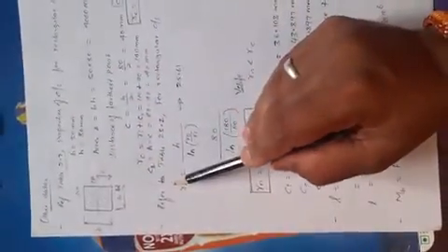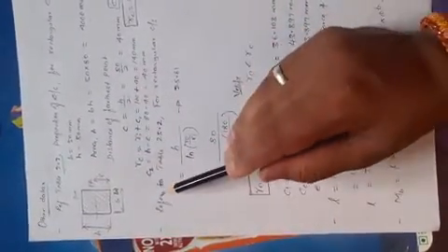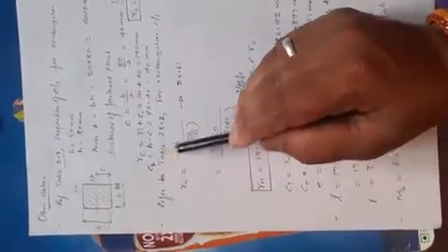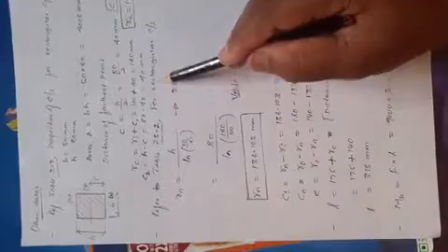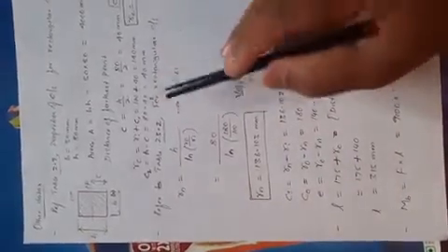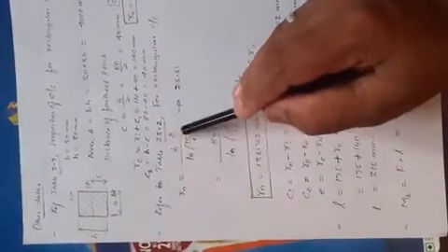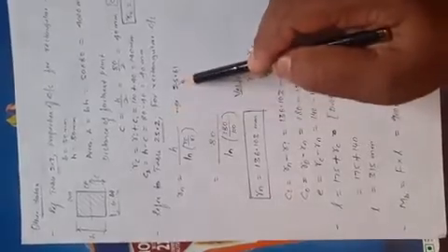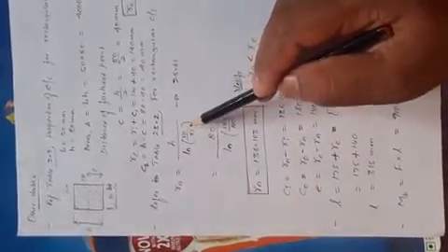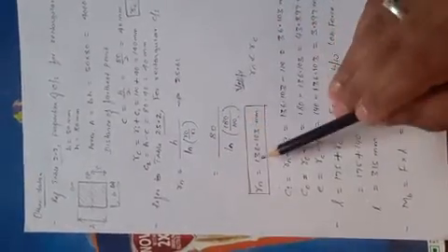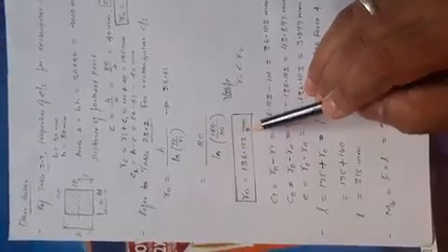Similarly, another data is Rn. How do you calculate Rn? Now refer to Table 25.2 from Volume 2 for rectangular cross section. The Rn is equal to, this is the formula, equation number 25.61. H we know, Ro I also know, Ri we know. Now substitute, you get Rn. The radius of the neutral axis is 136.103 mm.